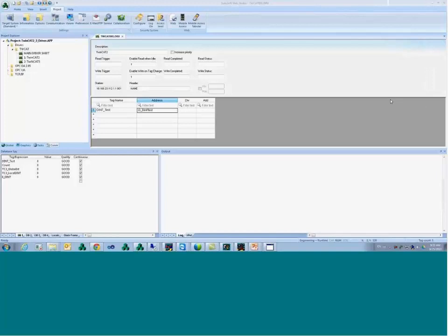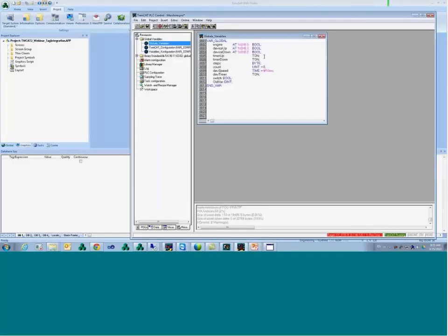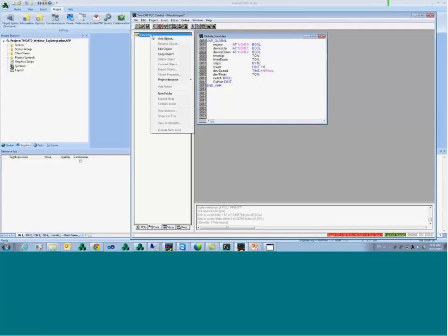So I got a question about tag integration with classes. We have an example here. How does that work? When you create a structure on the PLC, I go to my PLC program, and I have a tag that uses the timer on delay. That's a structure from Beckhoff. Or I can create my own structures, so I can create a data type here.